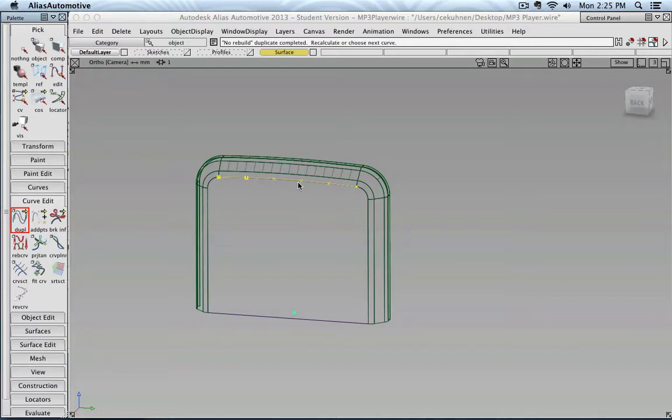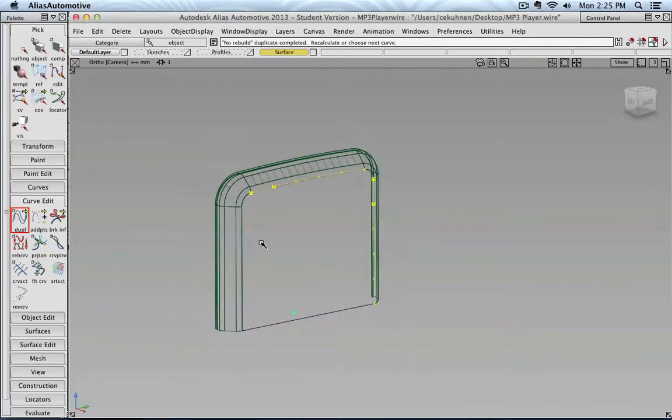And you see that this way I told Alias to select this lower edge of that fillet surface and duplicate it. I can do the same, for example, here with the left fillet, and let's rotate and then left click, move the mouse to the fillet piece, release the mouse button, and now I have those three curves extracted.